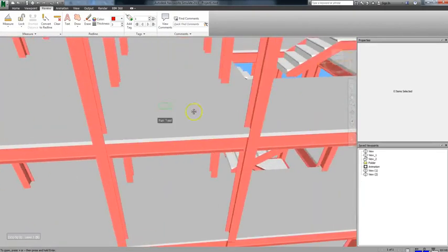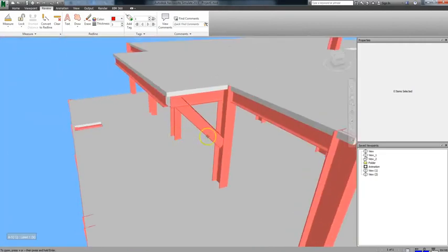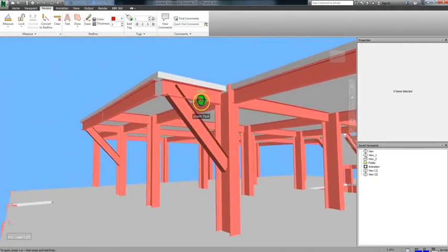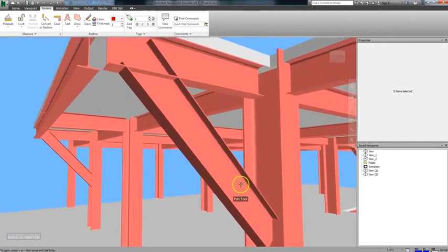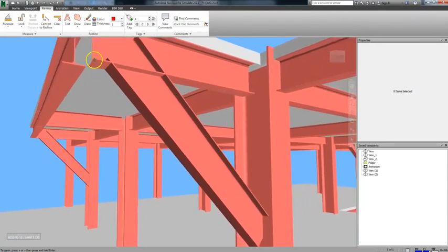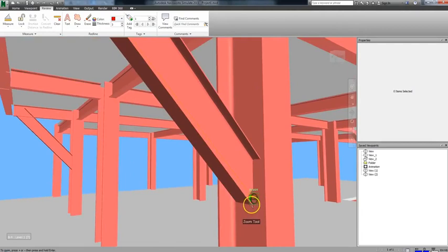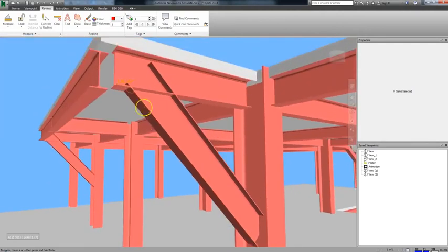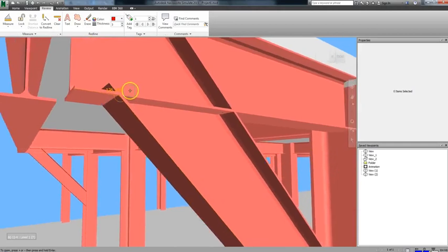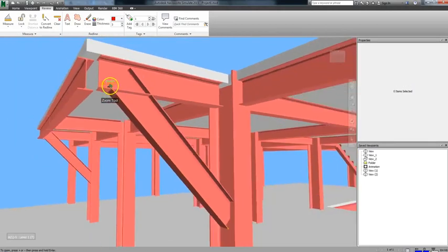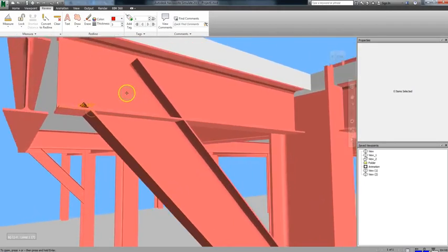One thing to note though is that we don't have to click just on vertices. You can click on any 3 points and it will take the angle measurement. So here, we're going to try to measure this obtuse angle as closely as possible. But if we don't exactly hit the vertex, it'll still be pretty accurate. And there you go. It is 136 degrees. Note that I'm just estimating. Navisworks actually gives you very precise angle measurements.